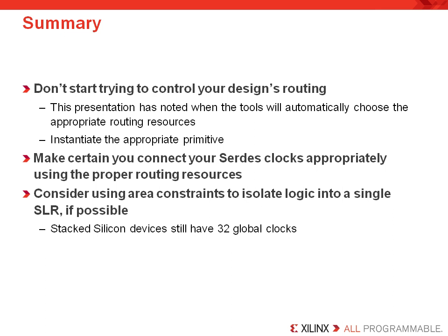But be clear here, make sure you instantiate the appropriate primitives in your design when you want to get access to a particular resource. And that's the point of us showing those primitives in some of the slides. You should also make certain you connect your SerDes clocks appropriately using the examples that we covered already and using the proper routing resources which are reflective of the proper primitive. If you want to see other examples, you can check out the user guide and look for the Clocking Resources module, and you'll see some more examples.